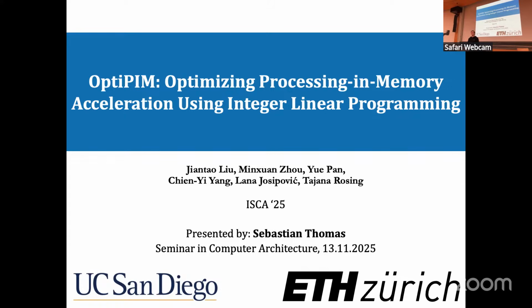Yeah, so I have a question related to heterogeneous computing. Normally, because near memory processing has got fabrication limitations, it has got weak compute capacity. So you always pair it up with some accelerator like a GPU or an ASIC. And how will OptiPIM work in that scenario? Because it can be that the data mapping that is required by the PIM can lead to more bank conflicts when it is required by the accelerator. So have you seen, if you ran OptiPIM, whether any such data mappings came up, and how it's going to perform in short?